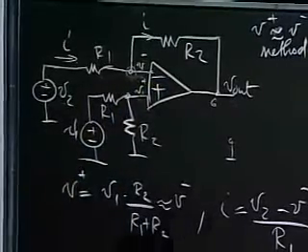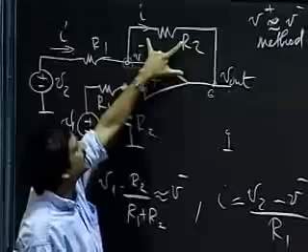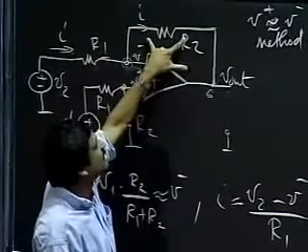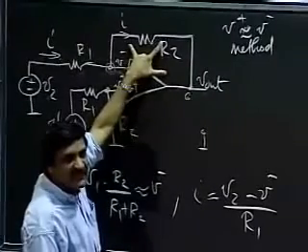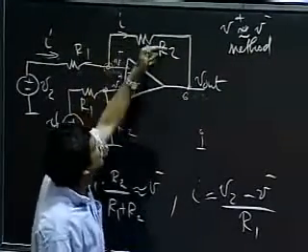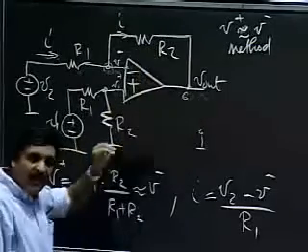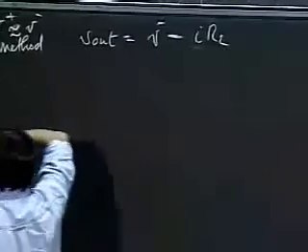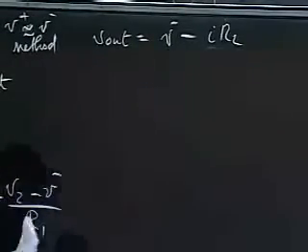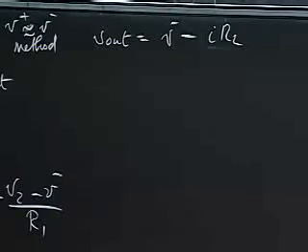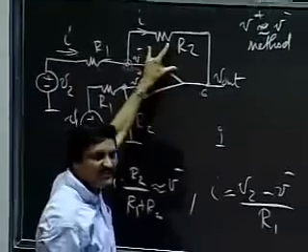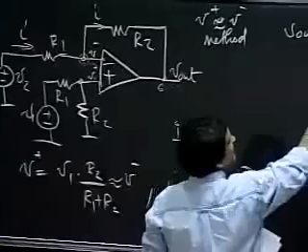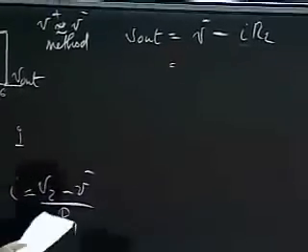One thing to be very cautious about, I'll tell you right now, is that the output here relates to the inversion of the voltage across this resistor R2. Be very, very careful: if I have a voltage across this resistor, that impacts V out with a minus sign attached to it. Notice that IR2 is the voltage across R2, and V out relates to the negative of that. That's one of the commonest silly mistakes I've seen people make in solving problems like this.